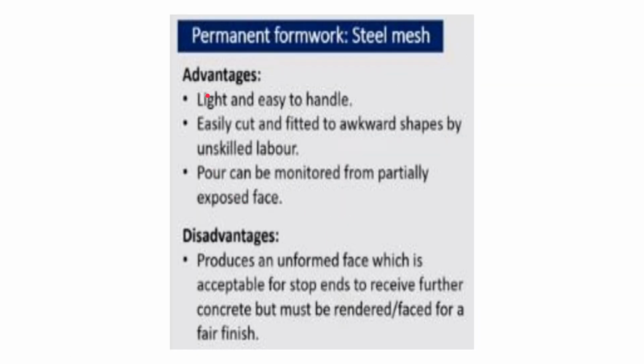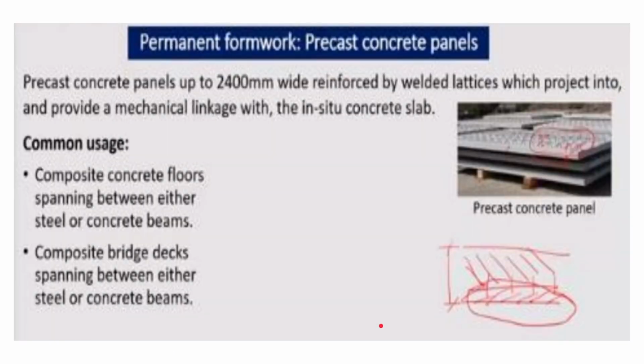Okay. So its advantage is that it is light and easy to handle, okay, and it is easily cut and fitted to awkward shapes by unskilled labor, okay. The pour can be monitored from partially exposed face, okay, and its disadvantage is that it produces an unformed face, okay, which is acceptable for stop ends like repetitive work to receive further concrete, but must be rendered or faced for a fair finish. So these are some of the issues, okay.